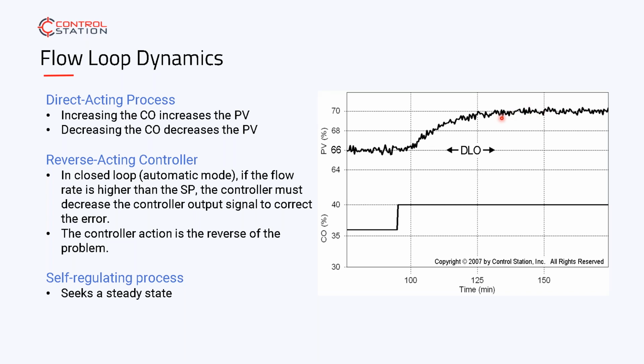Yeah, Brad, the majority of processes are self-regulating. The non-self-regulating systems are those level controllers, where if you open the valve, you'll fill the tank to the maximum rather than stabilizing out as with pressure, temperature, or flow. And the majority of processes seek to find that self-regulating state from that valve change. It's really finding that balance. What we want to try and do is be most efficient with that process.